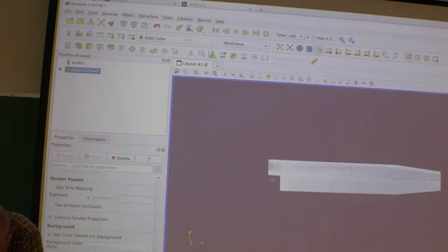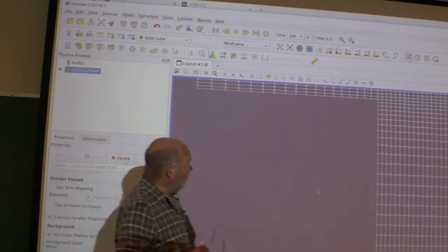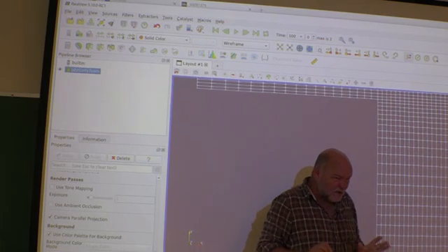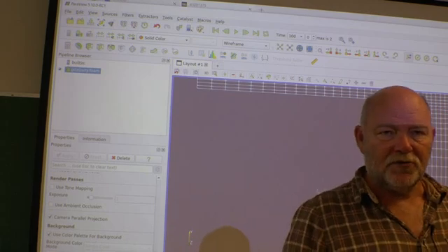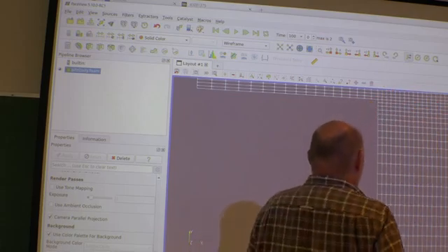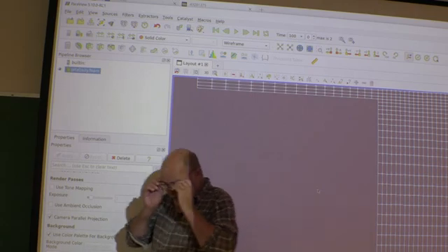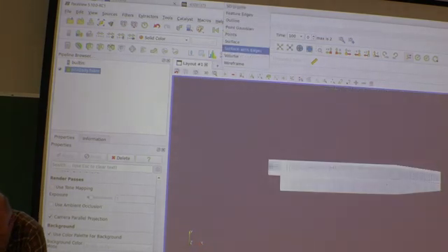So here, if we now zoom in, for instance, somewhere here, then you can see the mesh close to the step. Quite nice and smooth. A little bit of jump here in size. That's not so good. The mesh should be smooth and look nice. You shouldn't have too much change in area from one cell to the neighbor cell. But I think he can handle this one. It shouldn't be too hard. And the mesh, how it is constructed, we can have a look at it later.